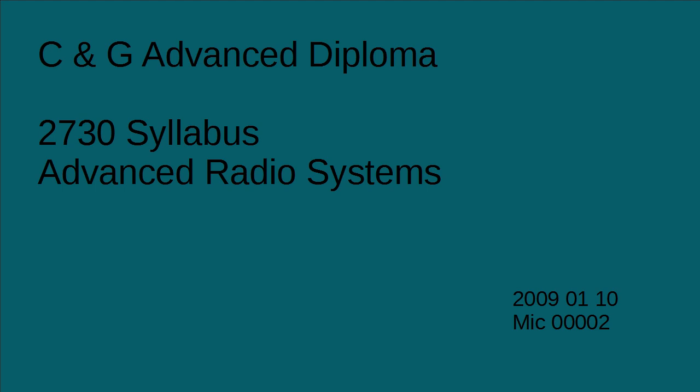So voltage is E into L, the electric field strength into the effective length. It is 0.0467 volts, and it is 46.7 millivolts. Usually these antennas will pick up either millivolts or microvolts. 46.7 millivolts.